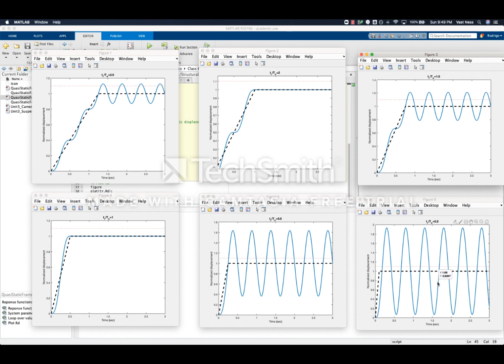So we have a general trend, as you can see, as the rise time gets faster, the oscillations get higher, which makes sense because if you think about it, as that TR tends to 0, the input function tends to a step input. And if you look back at the step response, you will see that it will go from 0 to 2, right?